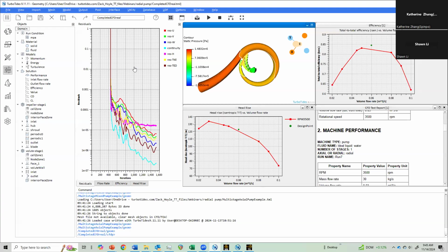So 1D is very useful in turbomachinery design, as it allows you to quickly predict performance of the machine under different conditions. CFD takes a while, testing is really expensive, but 1D models take seconds. But the challenge with using 1D models in performance prediction, of course, is that it's not always accurate. And that's because the 1D model correlations are empirical correlations that try to predict a 3D flow field using 1D parameters, which by its nature is not going to be perfectly accurate.